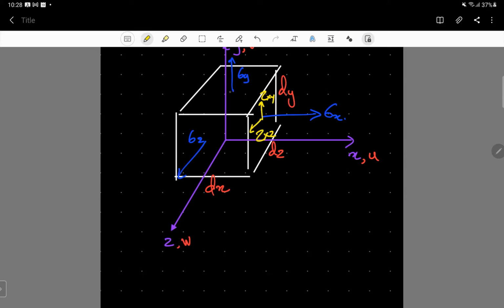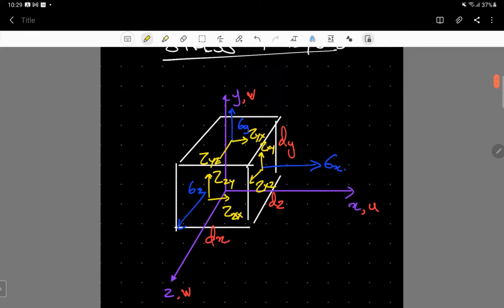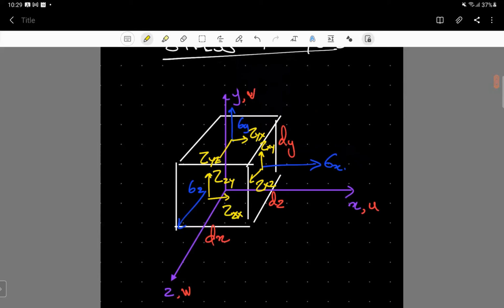Similarly, if we think of the Y plane, we can think of shear stresses acting in the YX direction and shear stresses acting in the YZ direction. Similarly, on the other face, we again have two shear stresses acting, in the ZX and ZY directions. I will upload a clearer picture when I upload the additional reading material, so for the moment, please bear with me with this figure.